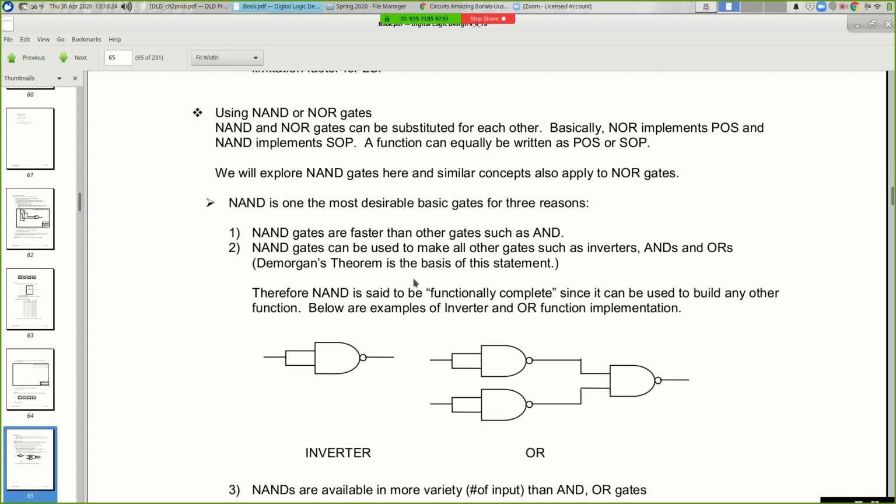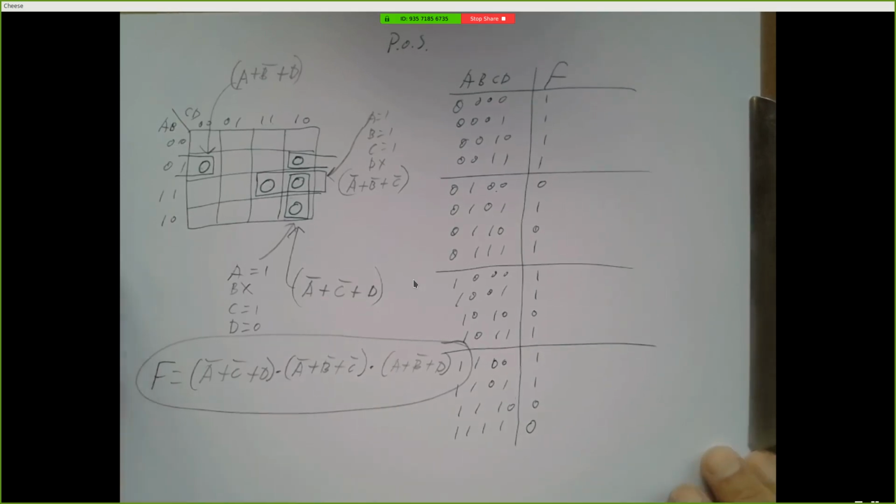And if a chip says that the gate has a fan out of 5, it means you can drive 5 inputs with it. And if you need to drive more, you need to do something to increase the current of that signal. It's not going to come up in TinkerCAD. But when you're dealing with these chips in an actual lab, just know that there's a limit to how much you can connect these things.